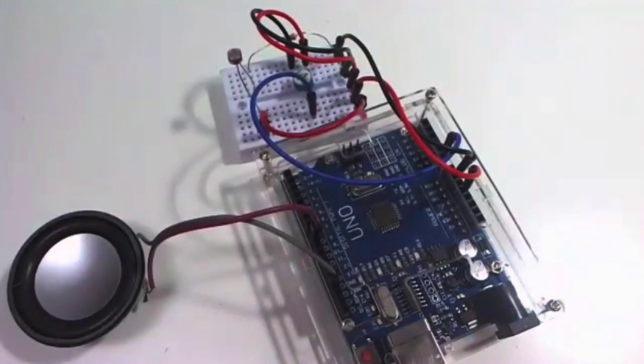Okay. So what it does is, this is the so-called voltage divider. It has a 5 volt and a ground. So when I turn this variable resistor, it will generate a different voltage, fed into the A0. And then the program reads it and will know whether it's close to 5 volt or close to 0. The program will use this analog value. It's not true or false. It's from 0 to 5 volts, to generate different tones to control the program.